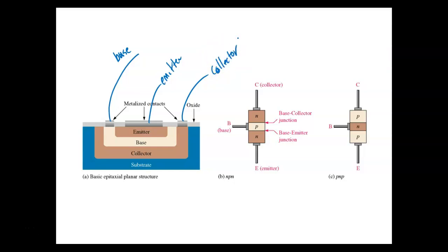So these are going to be 3-terminal devices. Every one of them, most of them, are going to have 3 leads coming out of them. We'll show you how to identify which one's which, and they can move those leads around. Some of them, the base might be over here and the collector, the emitter. You can identify the leads with an ohm meter, or you can look up the data sheet on it.